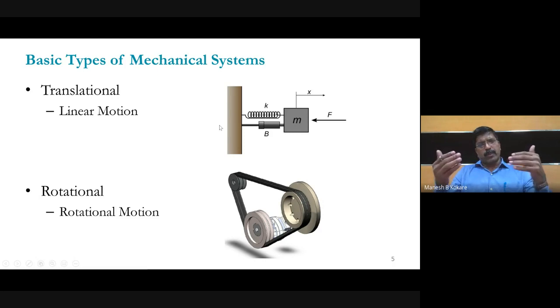So yesterday we studied how to find the mathematical modeling of an individual resistance, then an individual capacitor, then an individual inductor, and after that we connected the resistance and capacitor and found the transfer function of that. Then we can basically design any kind of circuit and find the transfer function by using the basic laws in that field.